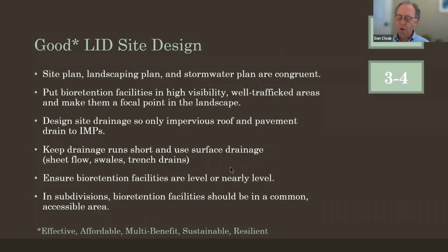If you're looking for a LID design that's going to have problems, find one where the runoff is directed into a storm drain inlet and then into a pipe, and piped somewhere, unless you have a steep slope and you're taking drainage from up gradient areas and you have a nice flat down gradient area, which does occur sometimes. But in general, you want to have that drainage just going across the surface and into a nearby bioretention facility.